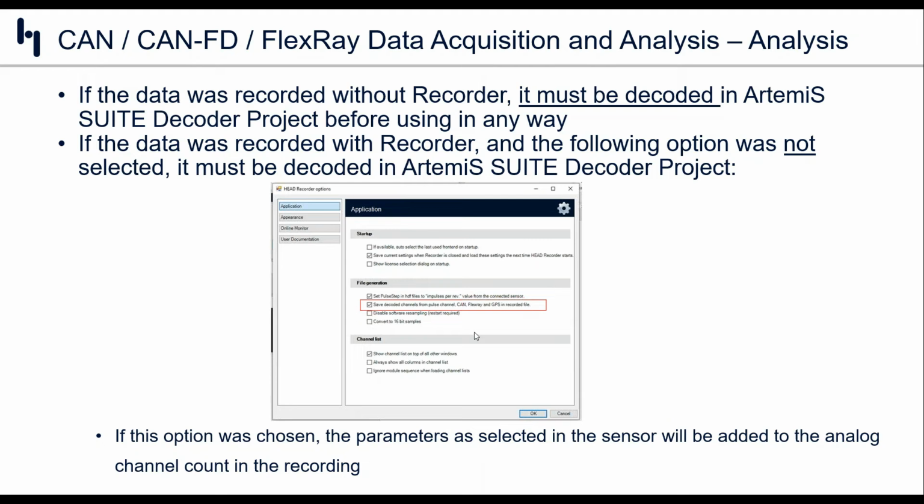In order to decode it, by the way, ASM24 will need to be selected in your license selector for your head recorder. So not only ASM00, but ASM04 in order to start recorder, and ASM24 will need to be recorded. You can record the whole CAN stream if you want to without ASM24, but you cannot live decode what it shows here without that ASM24.